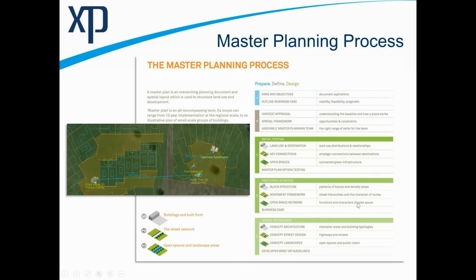Now, this is all earthworks and landscaping. So if we can multi-benefit from that work, then we can build in the surface water management, the sustainable drainage approach right at the very beginning. And this is one of the shots of something I'm going to show you very shortly, where we're actually mapping out the amount of space that a structure like a bioretention area or a pond or a swale or permeable paving will take up.